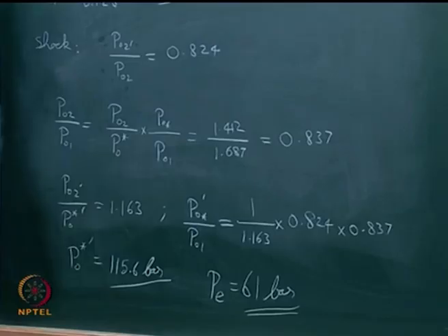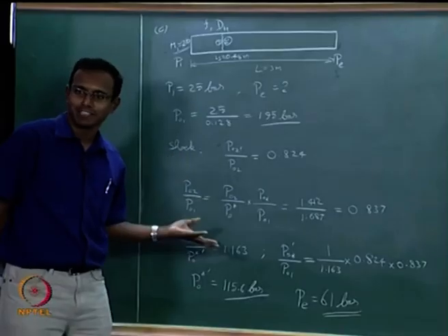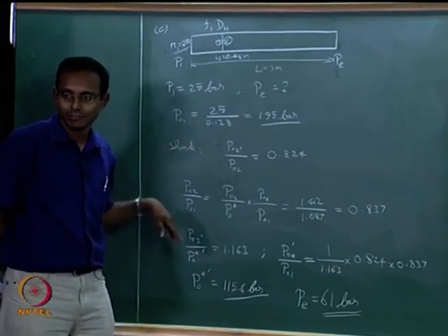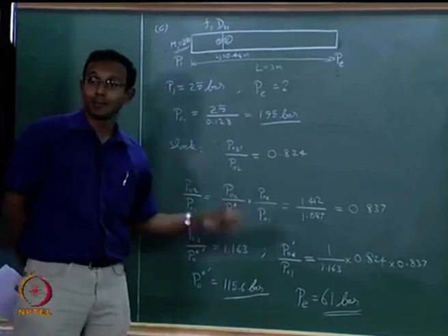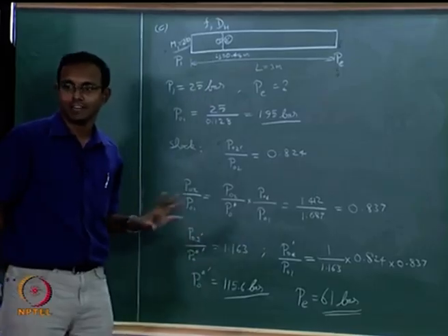Now of course it looks like I went through a little bit longer path because it is P naught. I wanted to solve a problem in class with P naught variation, so I went through this. I could have solved it with P star, then I would have avoided going to my isentropic tables completely. That is the only difference.